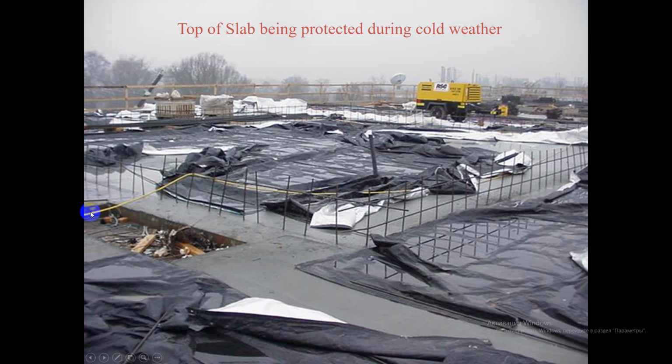Top of slab being protected during cold weather, you can see here. Using polyethylene to prevent evaporation or sprayed with a curing compound. This latter material again prevents evaporation from the concrete.